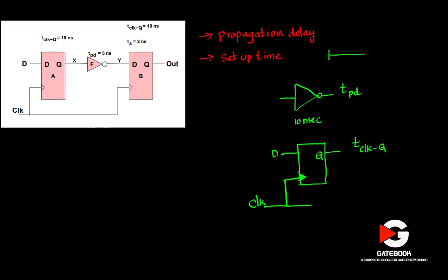Propagation delay is the length of the time. What it represents I will explain with an example. Take this inverter and let's say your current input is 0, and the current output is 1 here. When this 0 is changed to 1, immediately the output will not change to 1. It takes some time because the signal has to propagate through this. The duration of 10 nanosecond is required for the propagation. Then after 10 nanosecond, this would become 0, and as long as the input is 1, the output will be 0. So the change is permanent after 10 nanosecond. So that is a propagation delay.